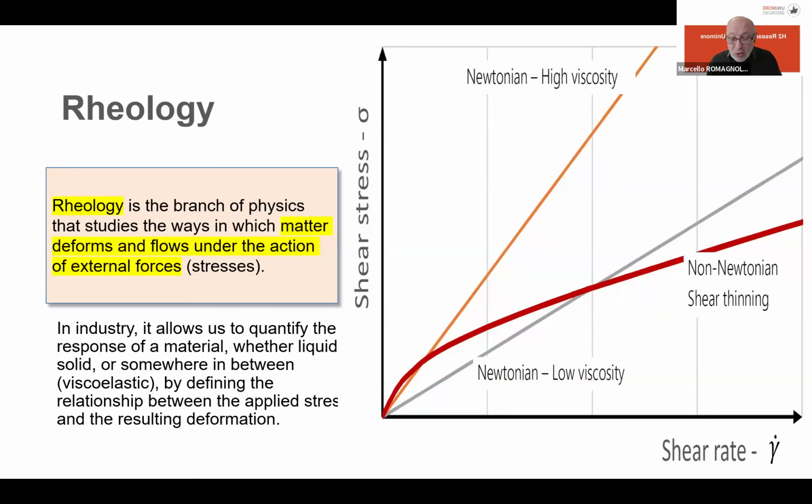Whether we are talking about simple Newtonian fluids like water or also complex shear thinning pastes, rheology gives us the mathematical relationship between the stress we apply and the deformation we get. This is a secret sauce for designing stable processes like extrusion, pumping of slurry, wet grinding, glazing, tape casting, slip casting, and so on.